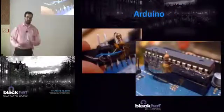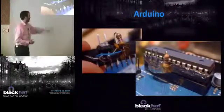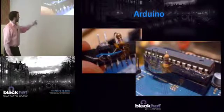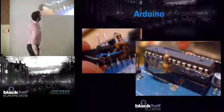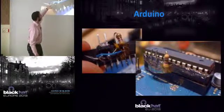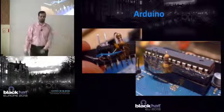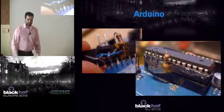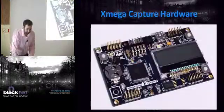You can even use an Arduino as a target. It is an AVR. It's almost the same AVR I'm showing here. And I've sort of hacked together a DIP socket with a resistor in one of the power lines. And then that resistor you connect up to your scope. So that's a sort of very low-cost type target.